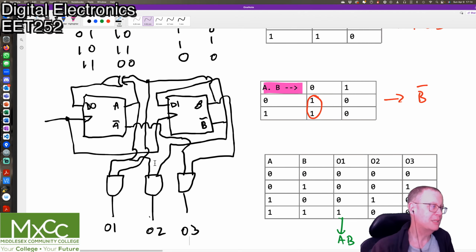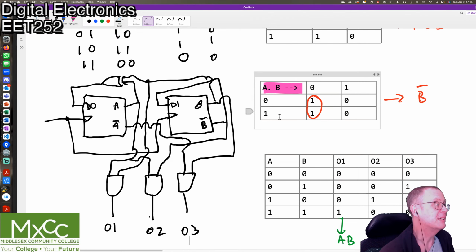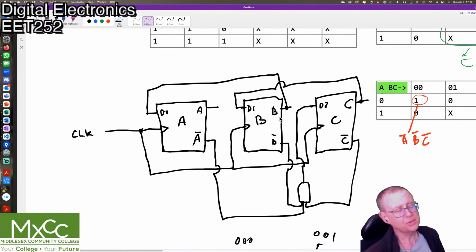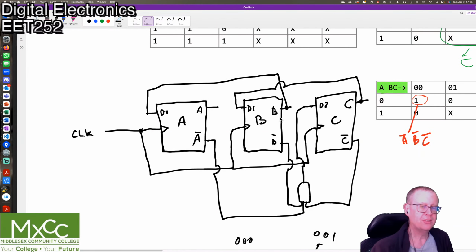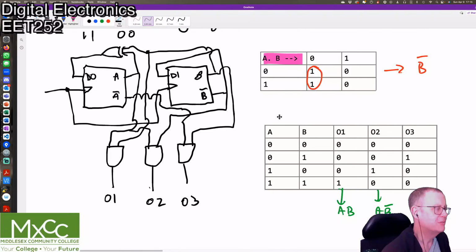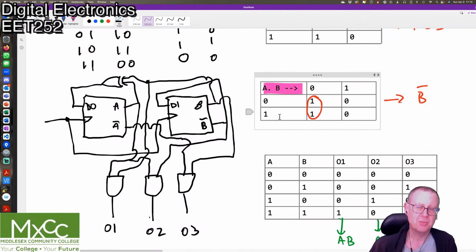So we'll have to look up, I think this one will require 3 chips, right? The exclusive OR gate, the dual D flip-flop, which is I think a 7474, and then a quad AND gate to get our 3 AND gates. Whereas this one will require also 3 chips. I think we need 2 7474s to get our 3 D flip-flops, because they're only dual flip-flops, the 7474. So 3 versus 3. It's much of a muchness.